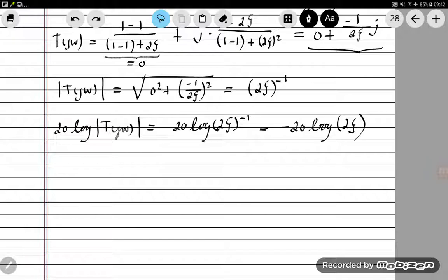Now for this specific case, when omega is equal to omega b, the look of this plot, or the behavior of this plot, will depend on zeta. And what this means is, if you remember, zeta is your damping coefficient or damping ratio, and that means the behavior of this magnitude function will depend on how much damping you've got in your system. For example, let's analyze a few values. So let's take zeta, minus 20 log of this 2 zeta.